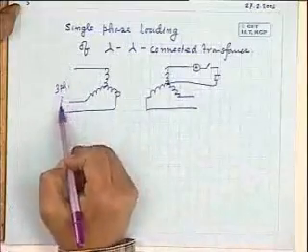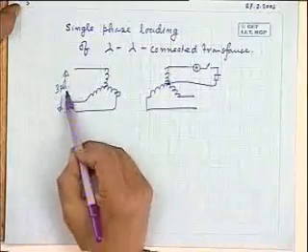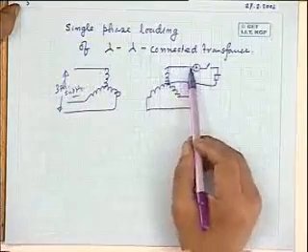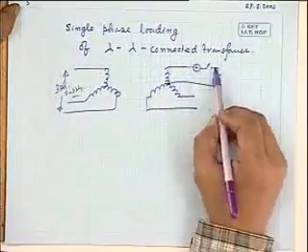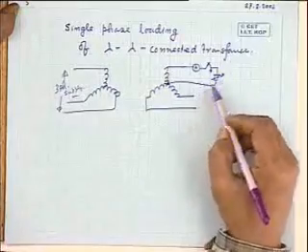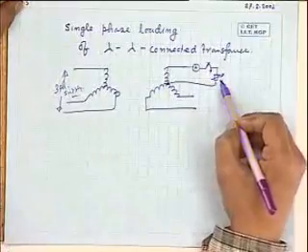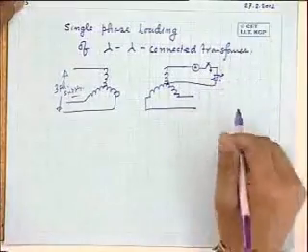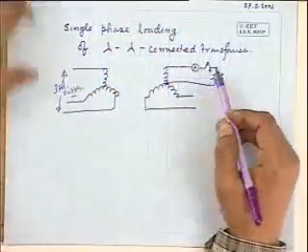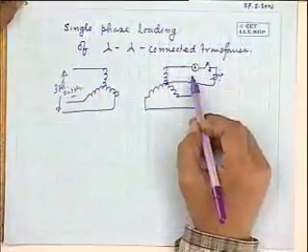Now what you will observe is that if you energize this 3-phase supply, here we will find induced voltage in all the windings, line to line balanced voltage is there. Now what you will observe, if you close the switch and start loading the transformer, that is go on reducing the impedance of the load. To load it means you have to reduce the impedance connected. What do you think your ammeter will read? One way to explain it: this per phase voltage divided by this impedance magnitude, this much it should read.